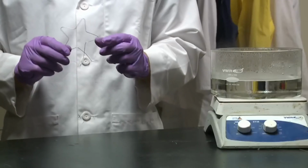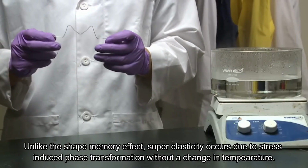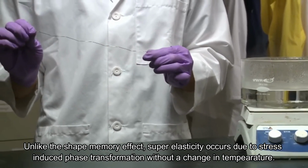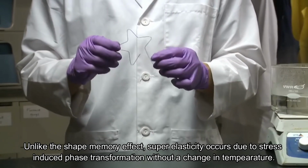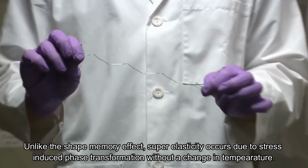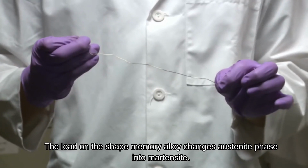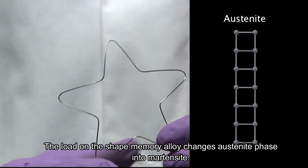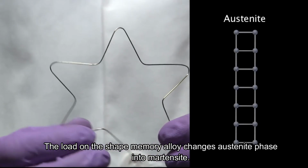Next is superelasticity. Unlike the shape memory effect, superelasticity occurs due to stress-induced phase transformation without a change in temperature. The load on the shape memory alloy changes the austenite phase into martensite.